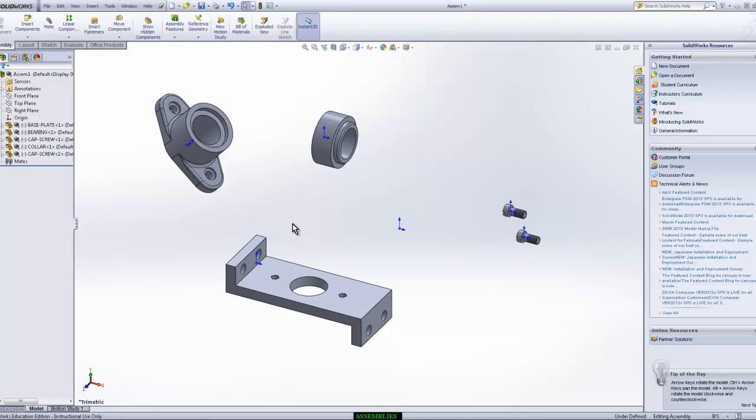It is my suggestion when you're starting an assembly to take one of those parts and determine it as the base feature or base part and lock or mate that part to the environment. These 2 coordinate systems are the same. This coordinate system I have selected here is the environment coordinate system.